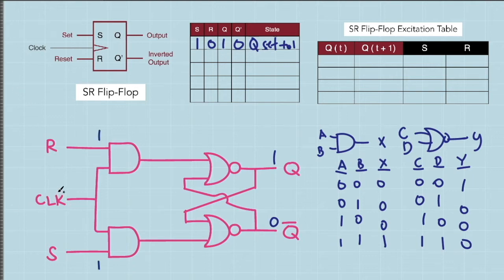And of course, during this instance, the clock gives a signal. So essentially, these inputs here are in logic 1. So this first NAND gate will have an output of logic 1. And since this is initially 0, 0 and 1 will produce an output of 0. And looking at this AND gate, this will produce an output of 1. And since this is 0, this will produce an output of 0.